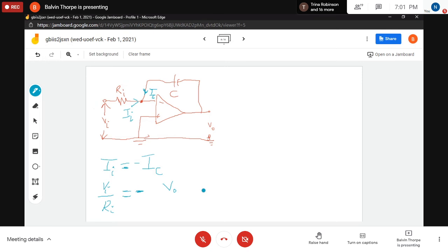Because of how a capacitor is, the capacitor takes time to charge when you apply a differential voltage across it, right? So the current will start from 0 and will increase up to the maximum possible current after the capacitor has charged. Therefore, the current across the capacitor is going to be at the rate of change of the voltage, right? When we talk about rate of change, what does that mean?